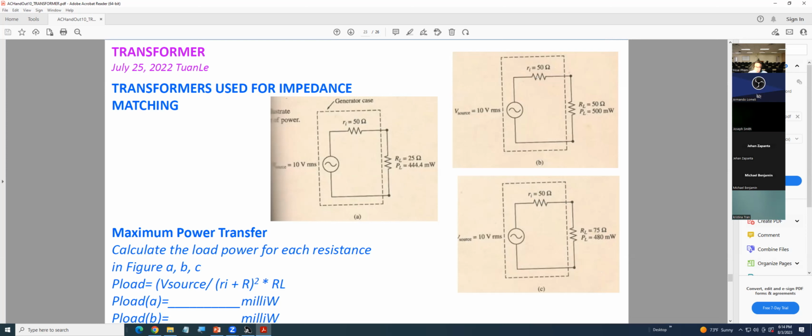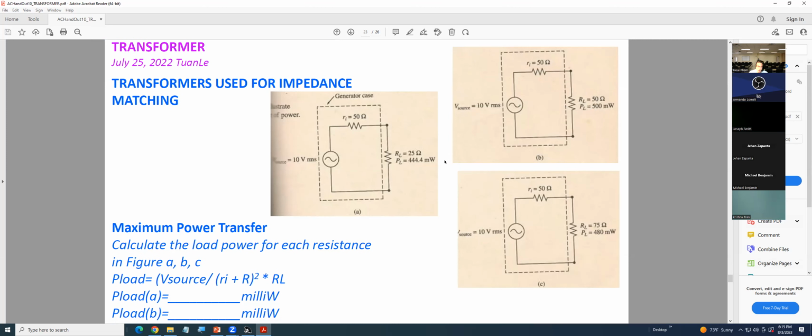And on that one, they get 50 ohm, 50 ohm, you get 500 milliwatts. That is only telling you one thing: the impedance has to be matching, 50 ohms here and that has to be 50 ohms, in order to get the maximum power. Input resistance and output resistance at the same value, then you get the maximum power.